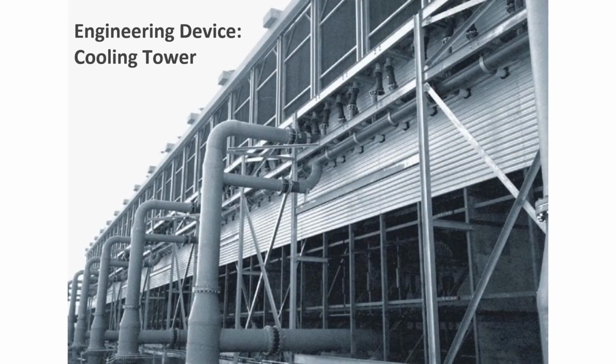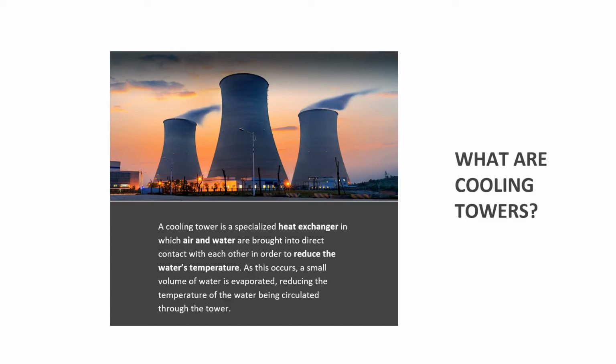The engineering device that is used in the humidification process is the cooling tower. So, what are cooling towers? A cooling tower is a specialized heat exchanger in which air and water are brought into direct contact with each other in order to reduce the water's temperature. As this occurs, a small volume of water is evaporated, reducing the temperature of the water being circulated through the tower.